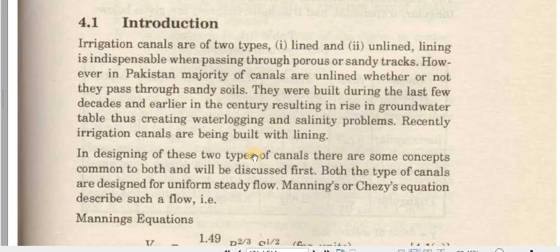If those sediments enter into the canals, they can reduce the discharge carrying capacity of the canals. So we cannot completely stop the silt entry into the canals, but we can minimize the silt entry into the canal at barrages or dams.